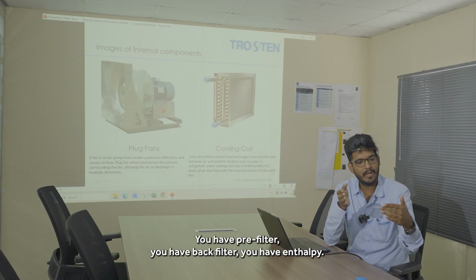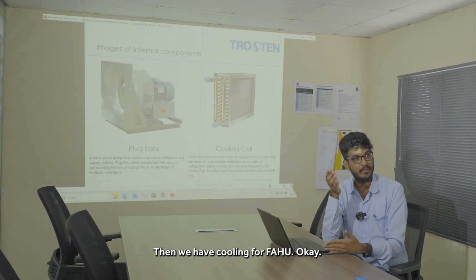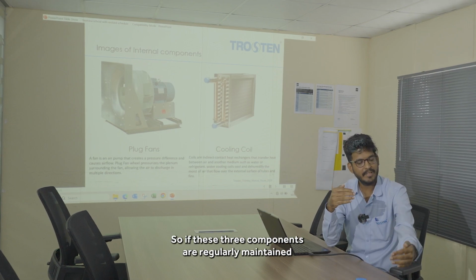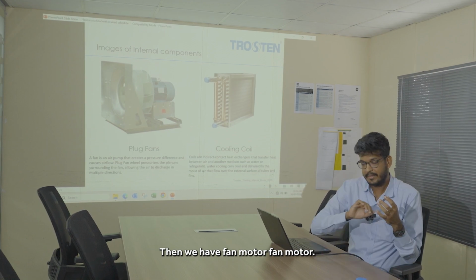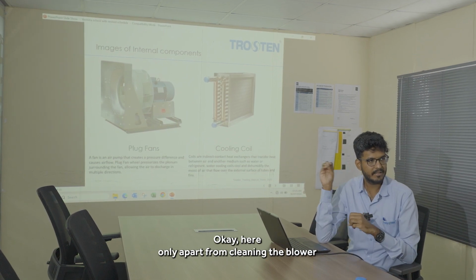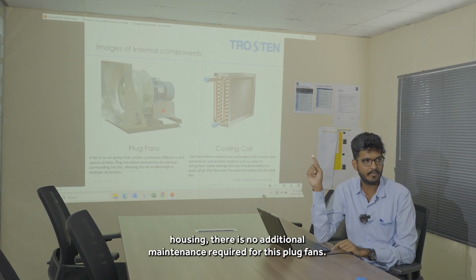For FAHUs you have a pre-filter, a back filter, an enthalpy wheel, then we have a cooling coil. Okay, so if these components are regularly maintained, yearly once is more than enough for us. Then we have the fan motor. Here, apart from cleaning the blower housing, there is no additional maintenance required for these plug fans.